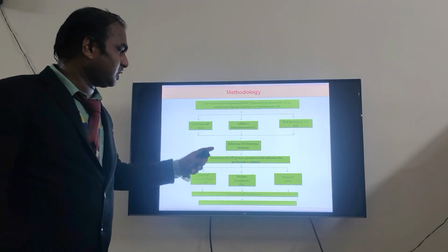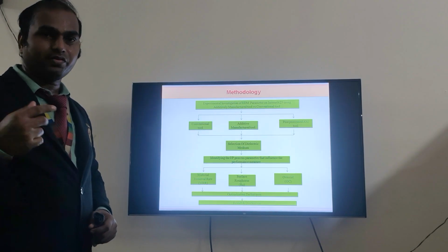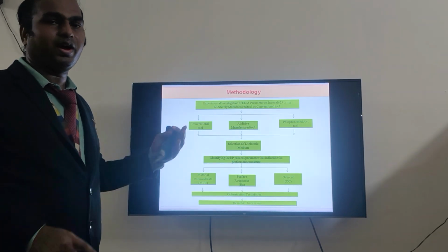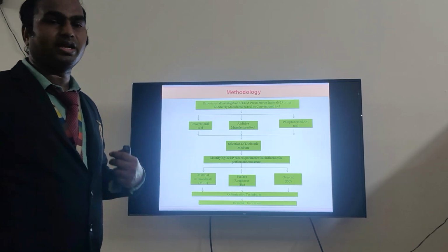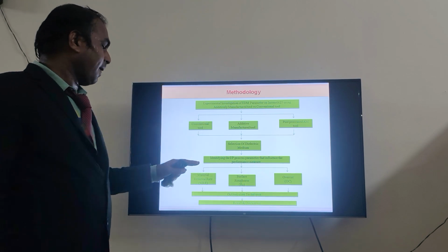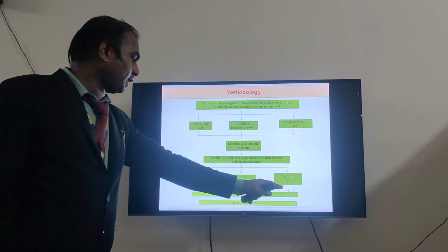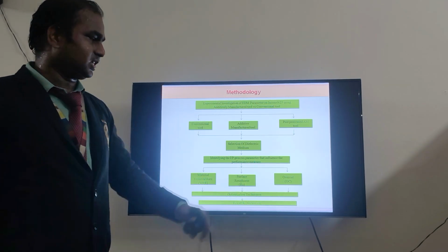The second process is selection of the dielectric medium, which can be of different types like kerosene, mineral oil, and deionized water. In special cases, we are going to use EDM lubrication oils. Next is to identify the input parameters over the output parameters like material removal rate, surface roughness, overcut, and optimization technique, and then we will have the results and discussion.